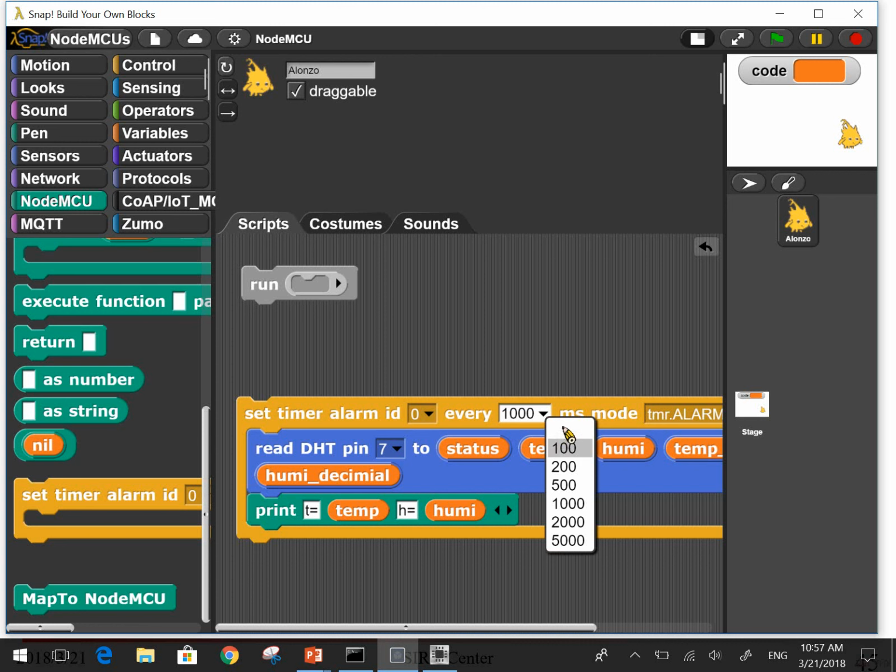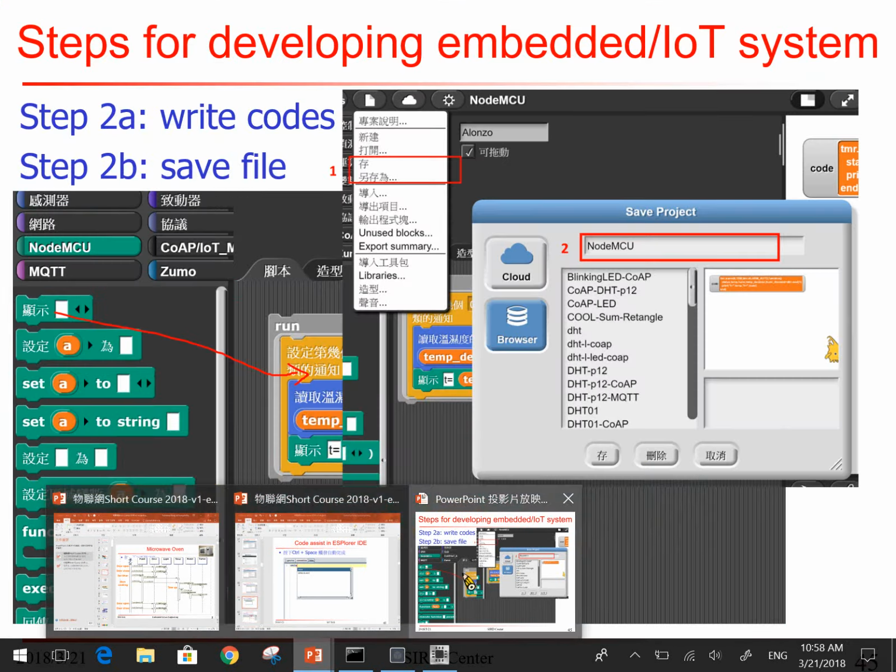So here, every minute we will run this program. It's similar to a while true loop, but you do something later. But instead of blocking the CPU, it is non-blocking. It's called an interrupt, right? So if you use delay, actually it's busy waiting. Suppose you have a for loop and you say delay something, then it's busy waiting. But this is some kind of interrupt. So when 1 minute happens, or 1 second happens, it will call this function. Okay. So this is writing the program as we mentioned here.